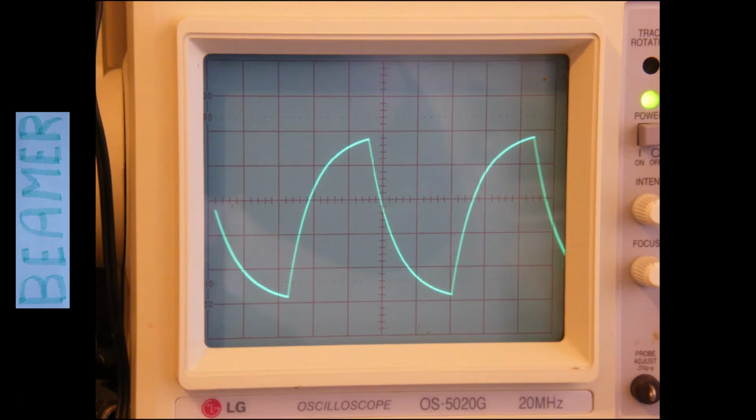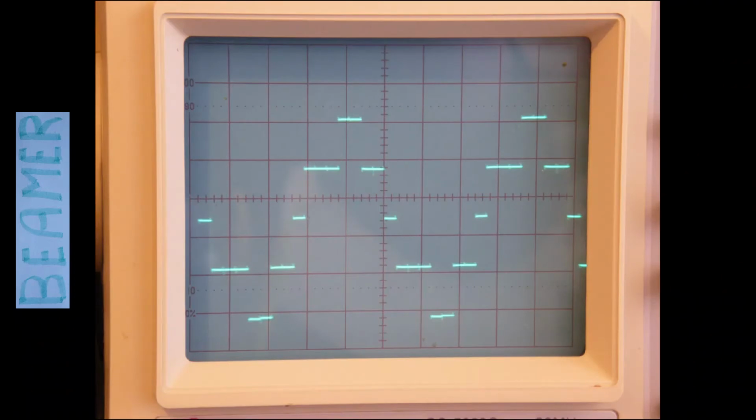Incidentally, the capacitance that I used on the integrator for this was 820 pF, though you can experiment with any value really. And you can see this is a classical exponential rise, exponential drop, typical sort of RC waveform from a square wave. And this is, if you like, an odd wave, where you can see you've got notches going down, notches going up, quite castellated really.